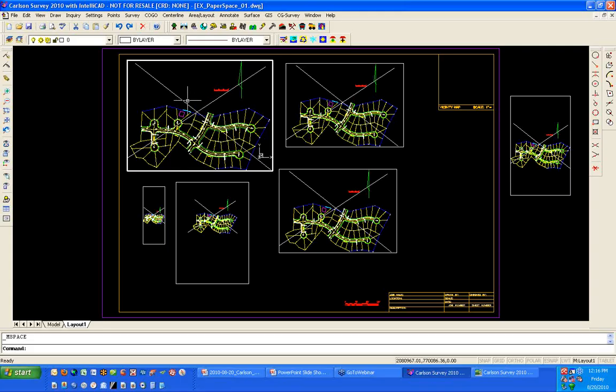A couple things you'll want to pay attention to. When I made it current, you'll see that the UCS icon is no longer down here in the bottom right in plain, and all of this works in AutoCAD as well. The icon in AutoCAD would be on the left. But notice when this viewport is made current, I have an icon here and not here.